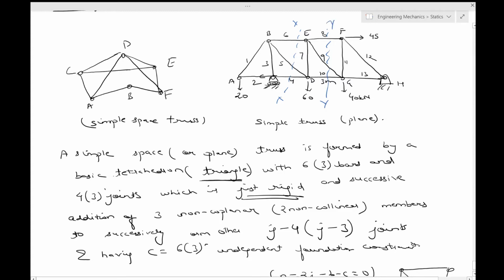So you can separately take up, like first take up the section on the right of xx, then take the section on the left of yy and draw the relevant free body diagrams, and then apply the equilibrium equations for this.